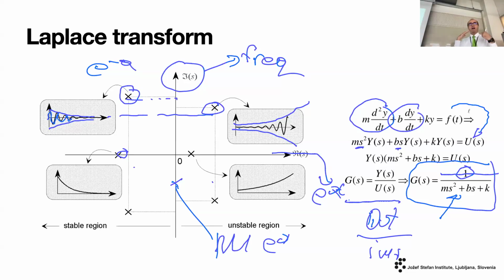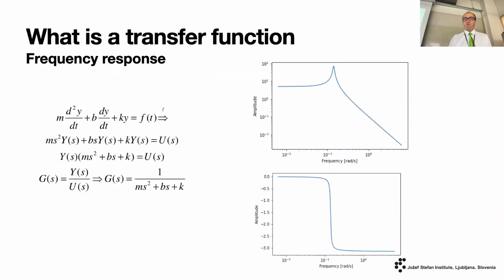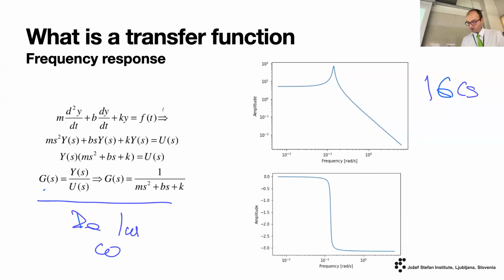So our ultimate goal is to find where our transfer function has these poles. This is everything that we need to know to characterize the system. So this is easier said than done. How can we do it? The typical way to do it is, because this is a frequency domain, real and imaginary over omega, we can write its amplitude, magnitude of g of s, versus frequency, and its angle, phase of g of s, over frequency.